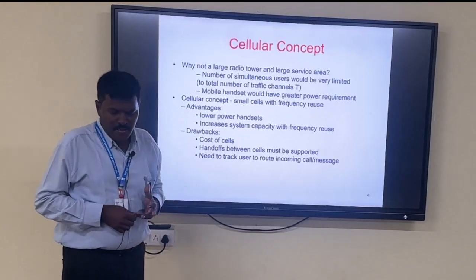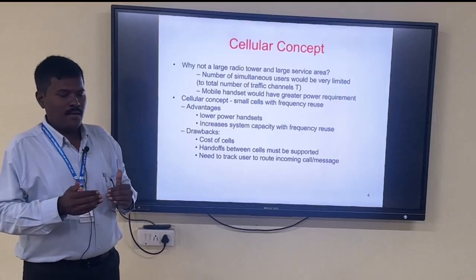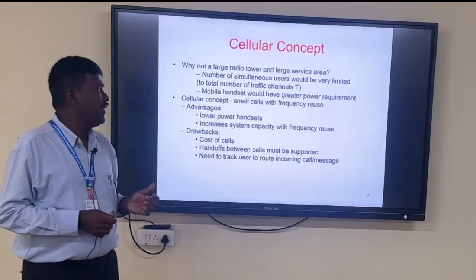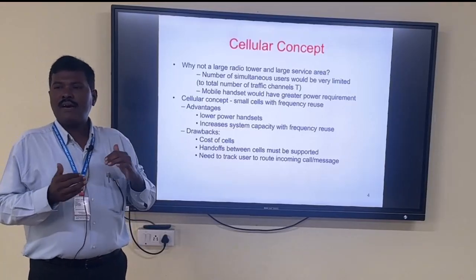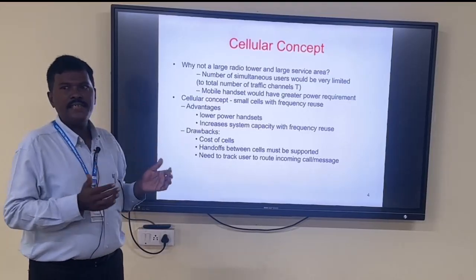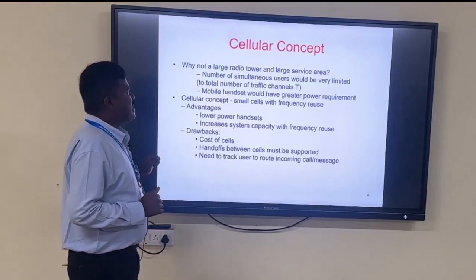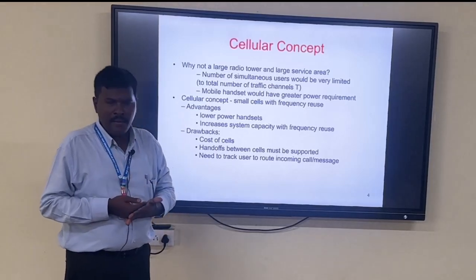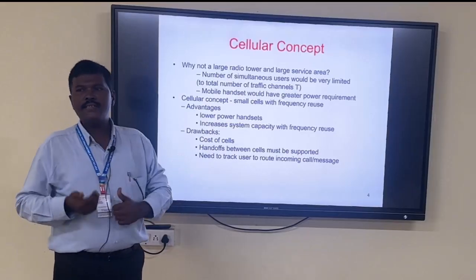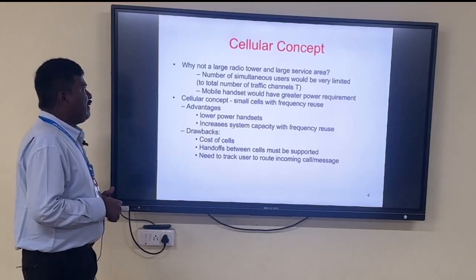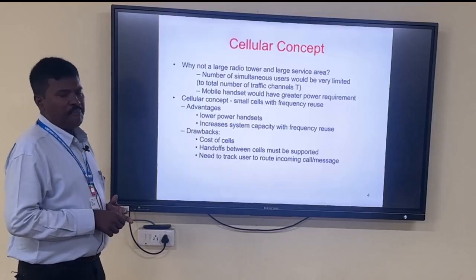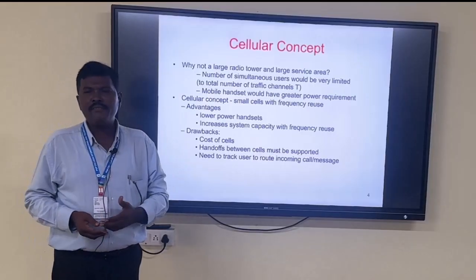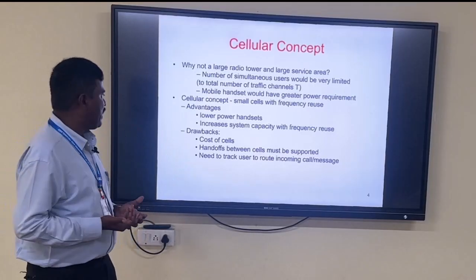The next thing is that the power requirement of the mobile handset would be very high. Based on this reason only, we go for a smaller tower size, and the cell size is also reduced. In the cellular concept, basically we choose smaller cells and the frequency reuse concept. The advantage of the cellular concept is that we can have low power handsets, and by using frequency reuse we can increase the system capacity.